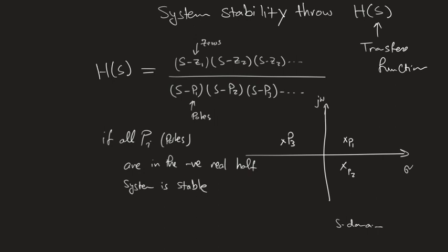We are not going to explore this too much because it belongs more to the control field, right? But people who study control, particularly I think electrical engineers, will explore this a lot. But for us, you just need to understand the concept that stability can be detected from the existence of poles. If they are on the right side of that complex domain, then my system is unstable. If I want to think of the simplest way to stabilize, I'll just place another 0 above the pole to cancel each other. Full stop. Okay? Not more than that, and conceptually.